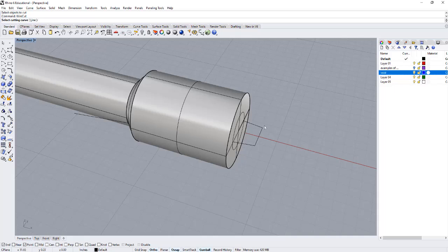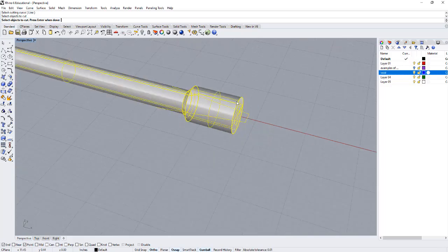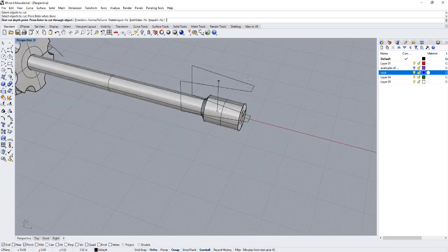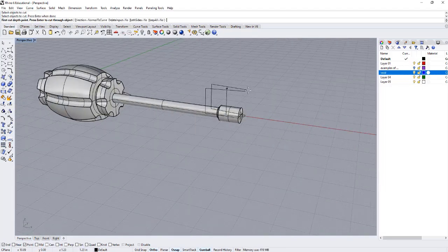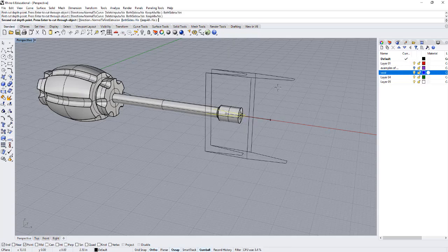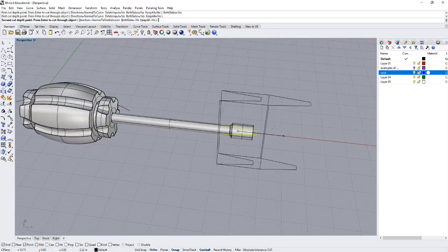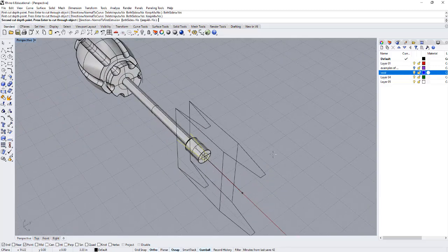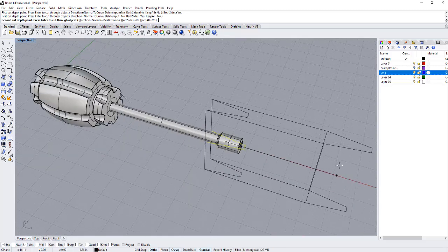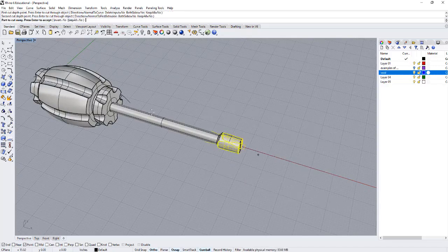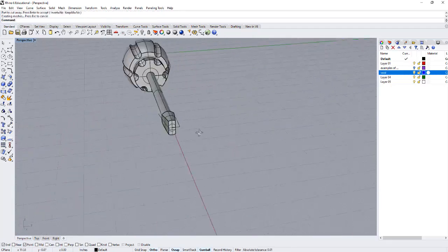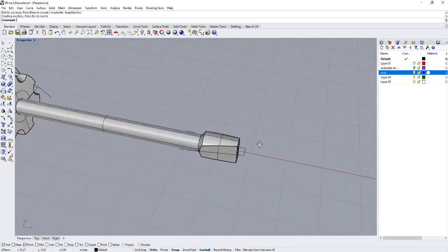I'm sorry. So wire cut, select the cutting object, so it will be my curve, and then select the object to cut. It will be that element, enter, and now I will cut it, but I want to cut it in both directions, so I'm going to say both sides, and then after that first click, I need another second click to create that void preview. So another click going forward, keep all, I'm gonna say no, enter, and then that fixes the tip of it.